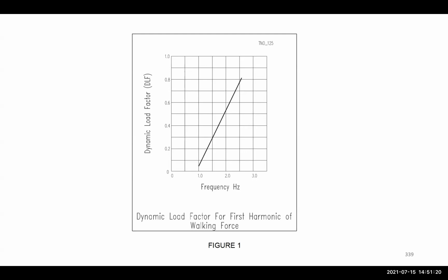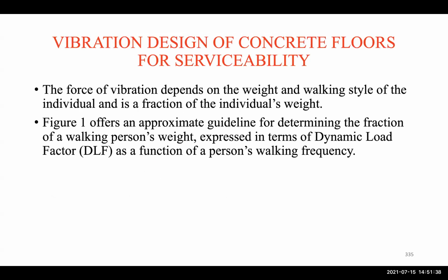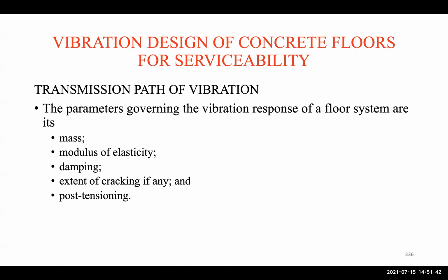It's the dynamic load factor as a function of the frequency. Okay, and that's the first harmonic of a walking force. So this is the dynamic load factor that can be used in the analysis. And the transmission path of vibration.